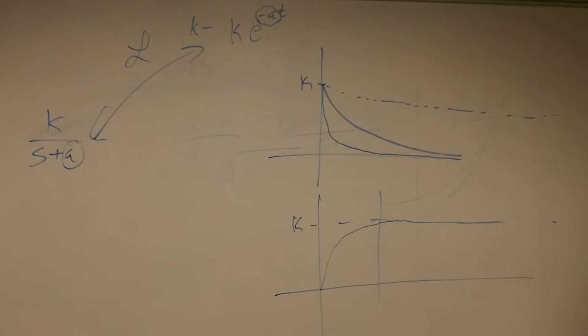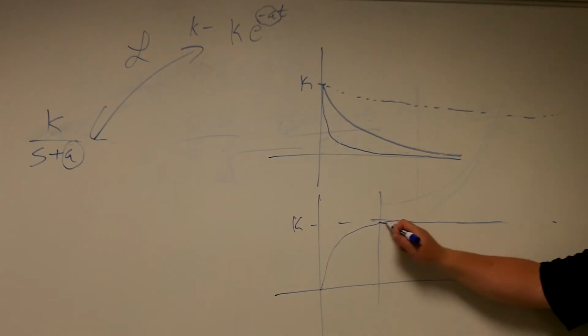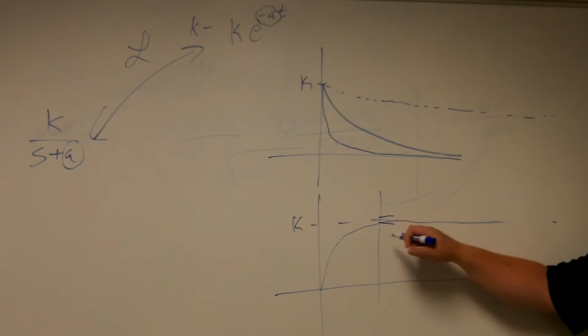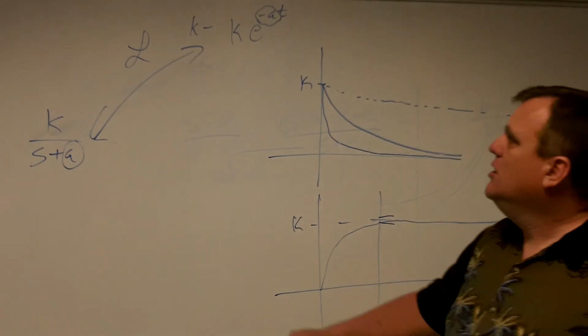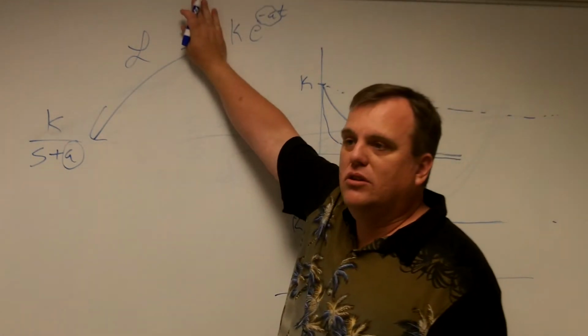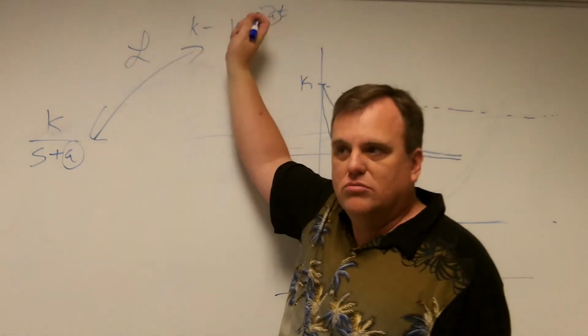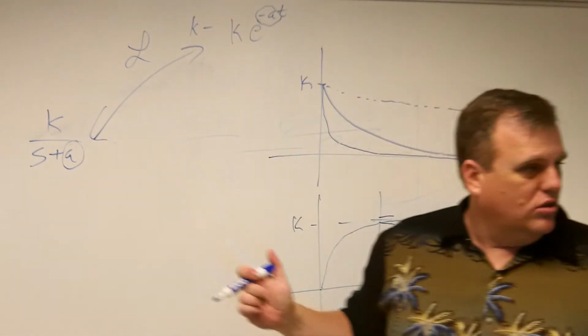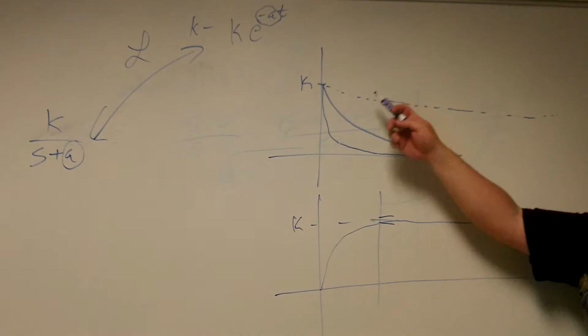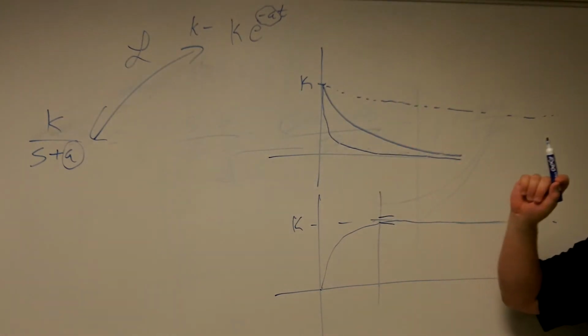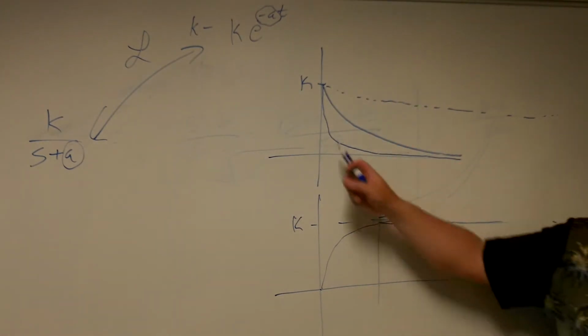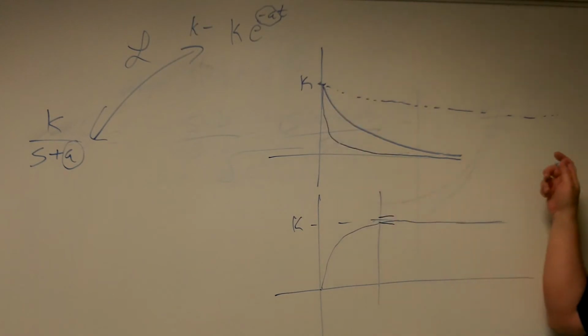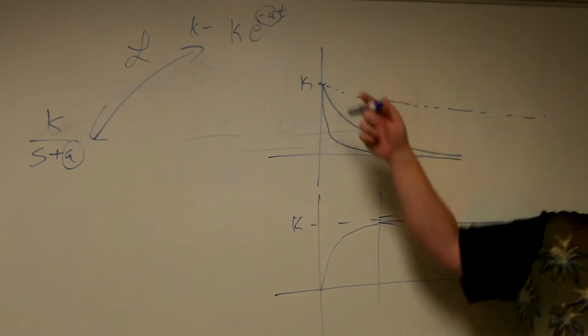You know, how long until this value is close enough to the final value. But realize, all you have to do is take a look at that, because these are the transients. Make sense? Is everybody familiar with how to graph quickly? You pick the starting value, you ask where it's going to, and then you get the shape of what's going in between.